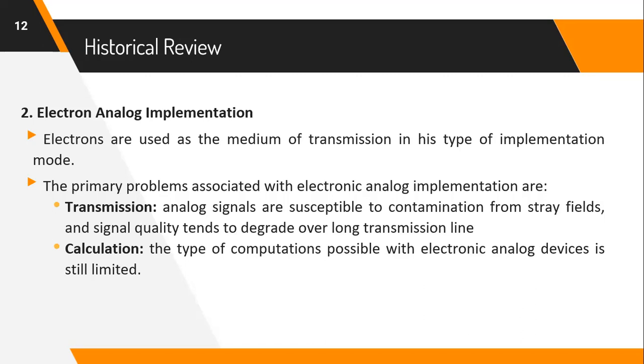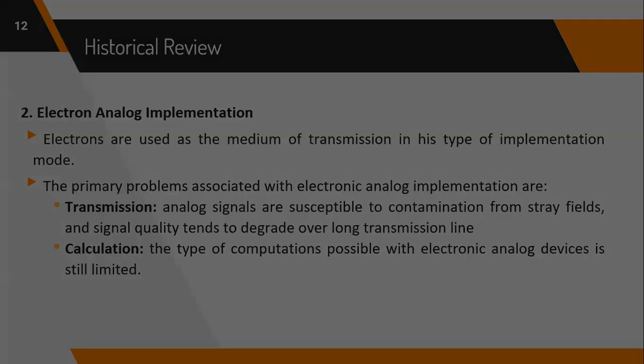Same as the pneumatic implementation, the electronic analog implementation also has two problems. In transmission, analog signals are susceptible to contamination from stray fields, and signal quality tends to degrade over a long transmission line. And in calculation, the type of computations possible with electronic analog is still limited.